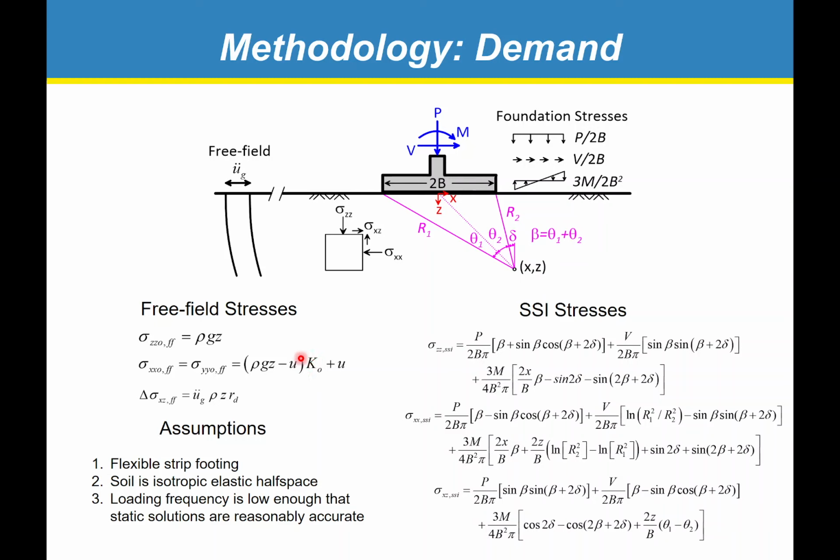So this is now the vertical effective stress times K naught, and then we add back in the pore pressure to get the horizontal total stress. So our stress equations are total stresses. We're assuming undrained loading conditions. It's hard to predict pore pressures due to these stress increments, so we're going to do a total stress analysis here. And then we get shear stress on horizontal and vertical planes, and we will introduce the traditional R sub D here. So it's surface acceleration times the mass density and depth times R sub D, right? So we can get that stress condition.